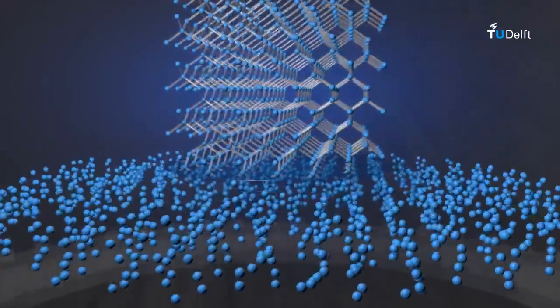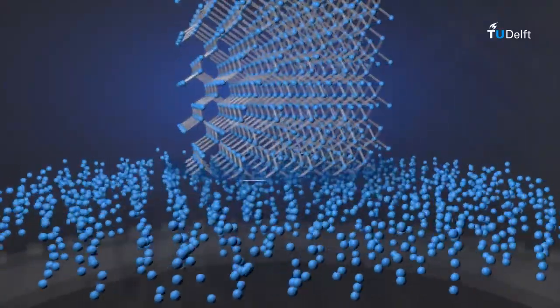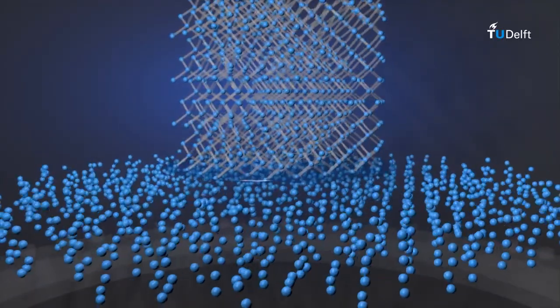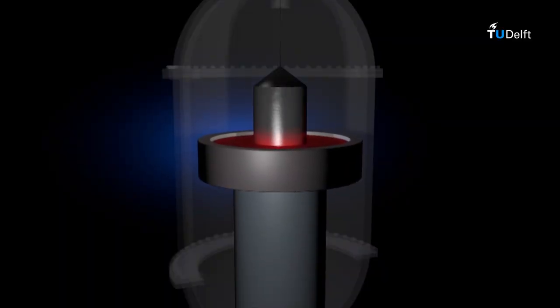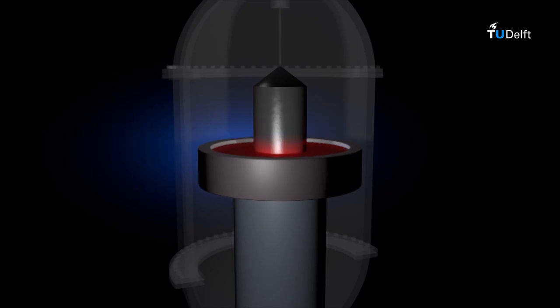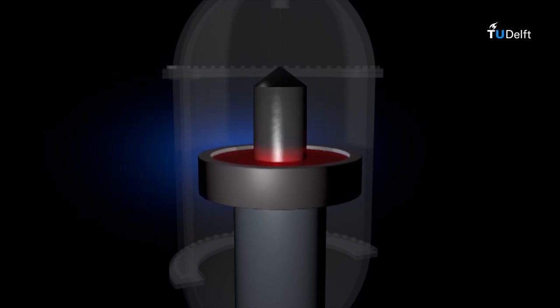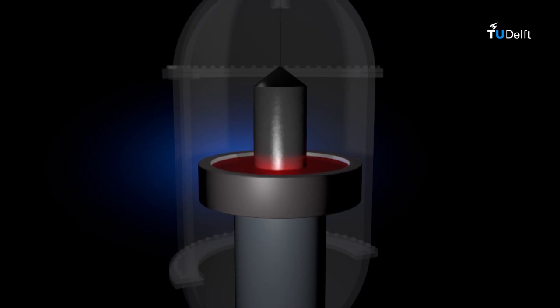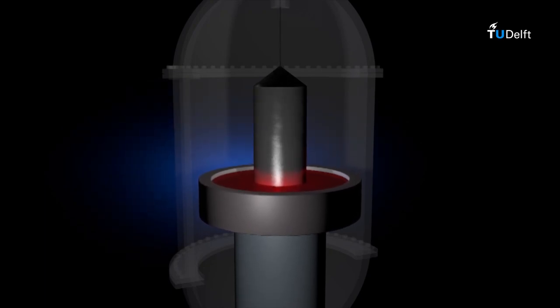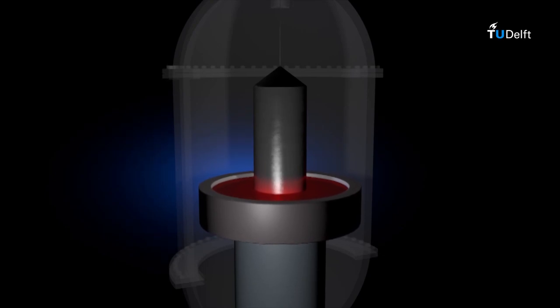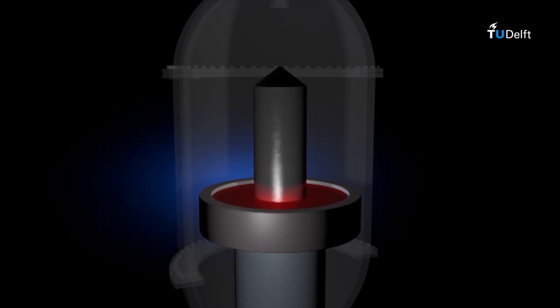This big single crystalline silicon block is called an ingot. In this process, the temperature gradients, rate of pulling up and speed of rotations are precisely controlled. This process is further developed through years of advances, and nowadays crystal ingots of diameters of 200 mm and 300 mm with lengths of 2 meters can be processed.